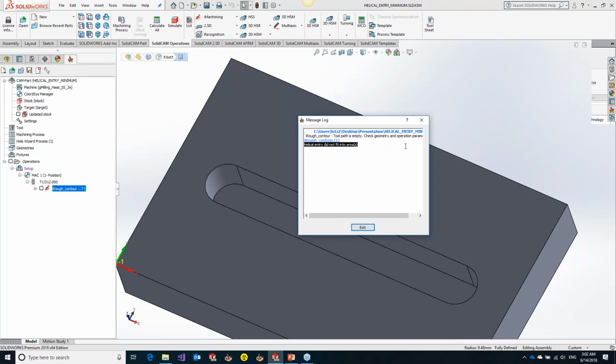We do this because helical entry is one of the more difficult things on the end mill, and you need good flushing. The harder the material, the more difficult it is. So we define that there should be a big size for the helical entry. The way to work around this is to use pre-drilling in iMachining, pick a smaller tool, or put a hole in your chain, and like pre-drilling, do some helical entry maybe from pocket or profile.